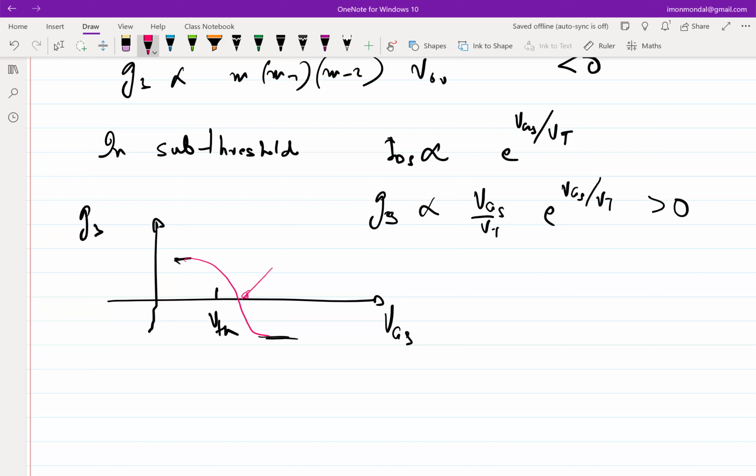Another argument in this favor is the option of trimming the circuit. Once the tape out happens and the chip comes back, if you have some variable bias and control of changing it, then maybe you can move the circuit back to this sweet point, wherever you want it to be.